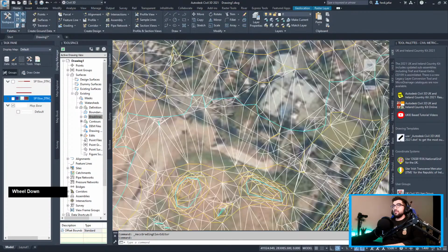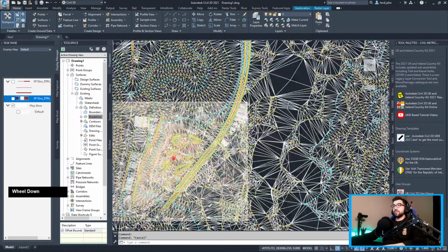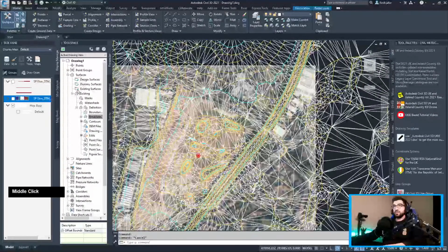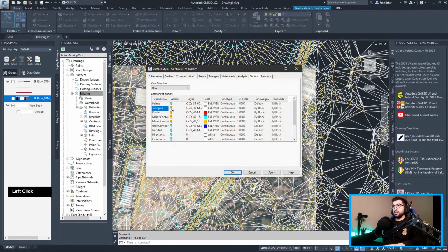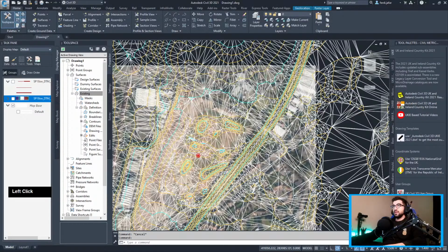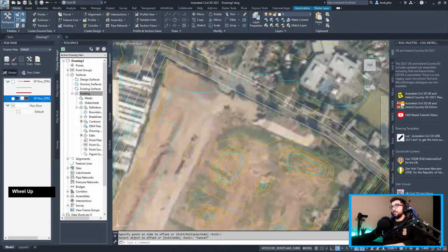And then what I'm gonna do is I'm gonna offset this one. Actually, I'm not gonna offset it. I'm gonna redraw my boundary. So I'm gonna freeze the triangles for now. Surface style, freeze the triangles. And what I'm gonna do is, since I have my original boundary there, I'm gonna offset it by 11 meters, let's say. Actually, maybe 20, just so you can see what's gonna happen.